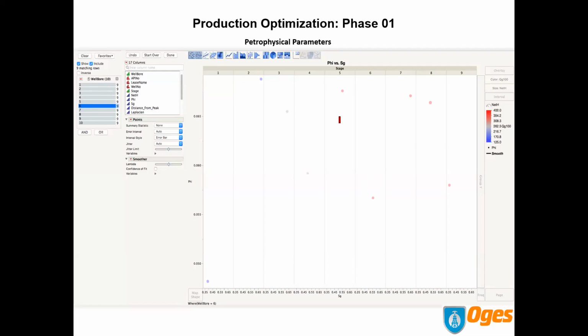This is important to note because some stages were producing water, and maybe they were producing only water. So if we wanted to drill another wellbore across this anticlinal structure, we could say, okay, stages, for example, 1, 2, 3, 4, if it was close to this particular wellbore that we're going to drill, we may not want to open them since we don't seem to be producing category 3 hydrocarbons.